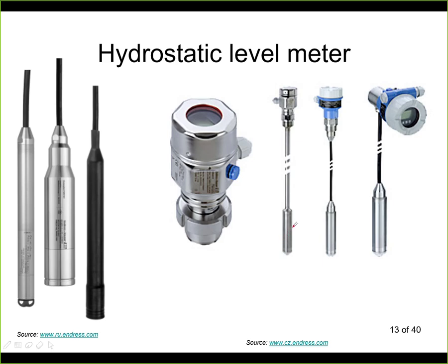Now, as I've already told you, this is not a suitable principle for applications where you have sediments. So with sediments, it's not working very well, because the sediments will very soon block the access of the liquid here to the diaphragm, and it will cause a malfunction of your liquid level sensor. But on the other hand, it works well with foam. Foam is on top of your liquid and not on the bottom, so it's suitable for applications where you have foam, for example.